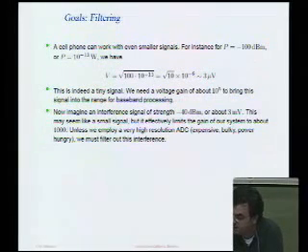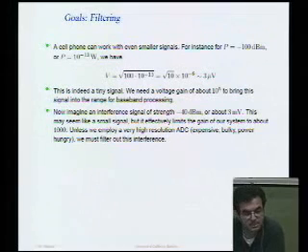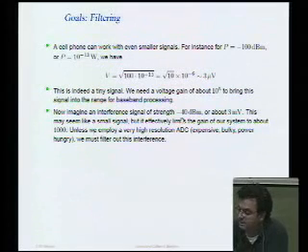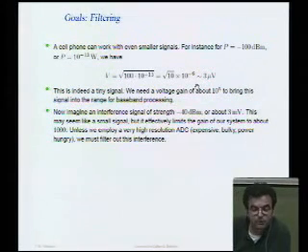But the problem is it's so much bigger, right? It's 60 dB bigger than the signal that we're trying to observe. And that means that if we just simply were to apply gain to our system, that interferer would actually limit the gain of the system to about 1,000. In order to take 3 microvolts, let's say, up to 300 millivolts, in order to digitize it, we need a gain of 10 to the 5.